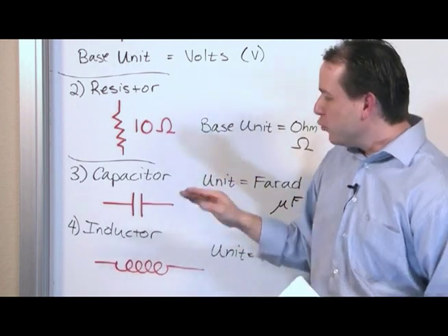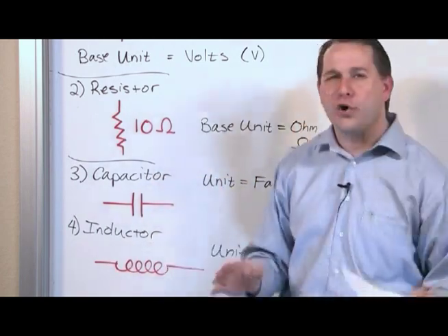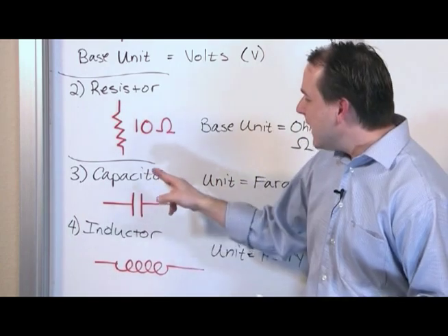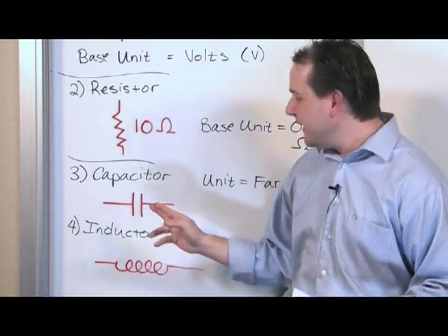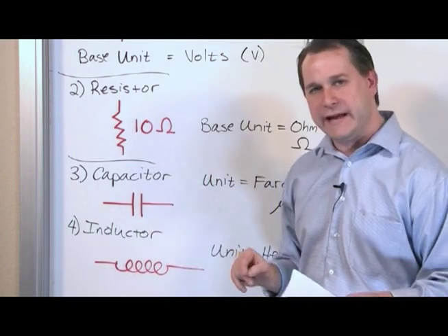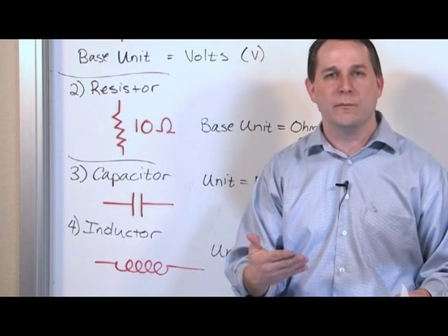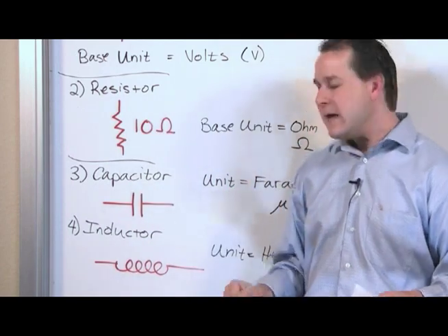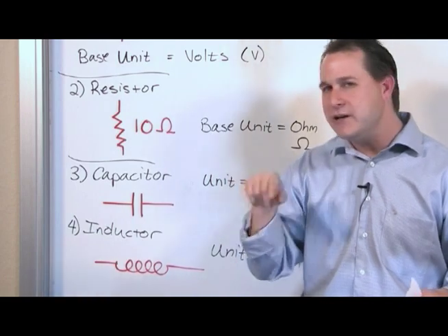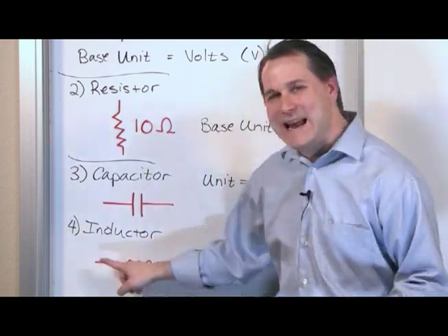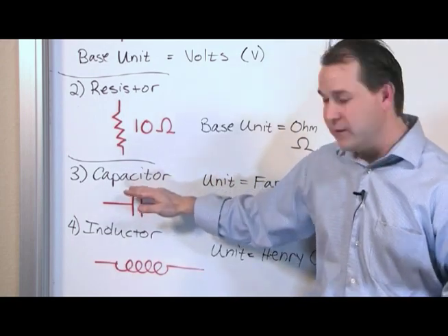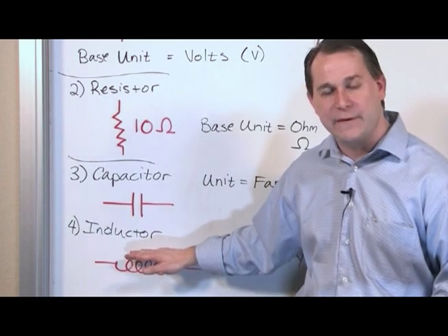Step back with me for a second and realize that a capacitor and an inductor are really nice mirror images of one another when you think about it, right? I told you a capacitor is constructed to basically concentrate the electric field inside the plates to store energy in the form of an electric field between the plates. The inductor is specifically constructed to store energy, but not in an electric field, as a magnetic field that's inside the coil. This guy stores energy as an electric field. This guy stores energy as a magnetic field.